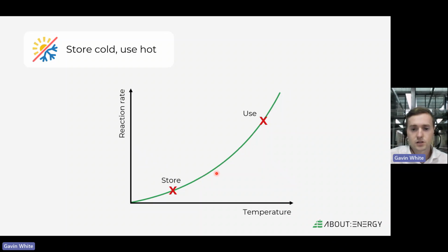A battery converts chemical energy into electrical energy whenever it's discharged. And these chemical reactions have to occur. Now, this chemical reaction rate is governed by what's called an Arrhenius relationship, which is an exponential with temperature. So for increasing temperature, the chemical reaction rate increases. And this is exactly why you keep your food in a fridge.